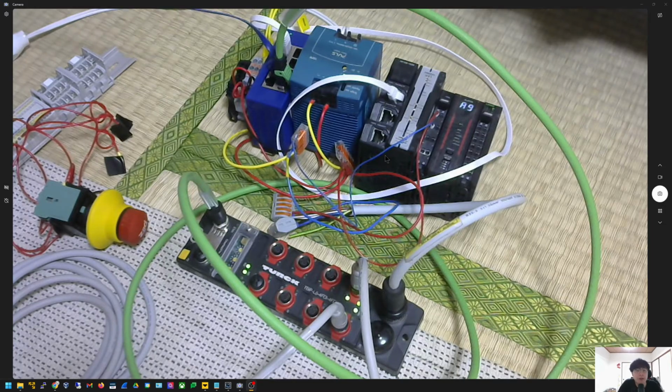Okay, here is the main configuration that I use in this tutorial, and here you see I'm using an OMRON CPU and it is an NX1. I forgot the real model number, and here you see there's an SL5700. It is a safety module to let you handle the CIP Safety connections and all the safety stuff. And here we're using a Turck CIP Safety IO block. So now it's in a running mode connection. We are connecting to an eStop. The eStop is from Pilz. And here is the input and this is the output.